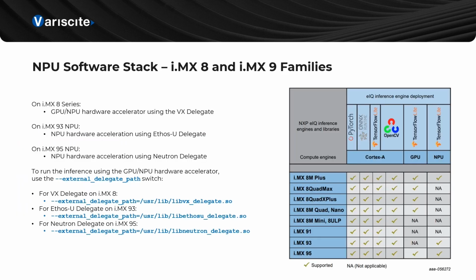Earlier in the presentation, I mentioned that it's possible to run inferences on the CPU, GPU, and NPU. Different software stacks and libraries support these capabilities depending on the specific NXP SoC. All Variscite SOMs in the i.MX8 and i.MX9 families can run inferences on the CPU. For GPU-based inferences, all i.MX8 SOMs except for the 8M Mini support the VX delegate.